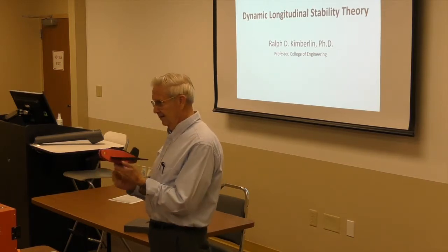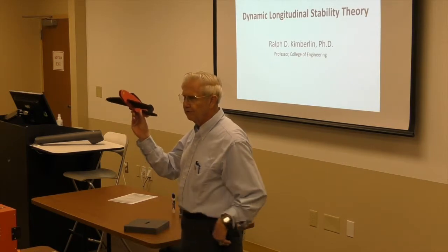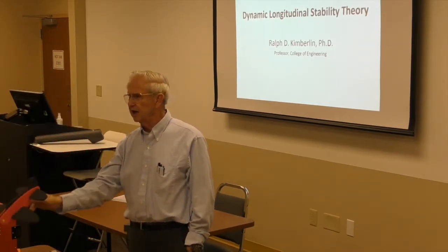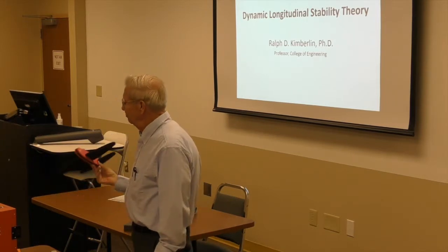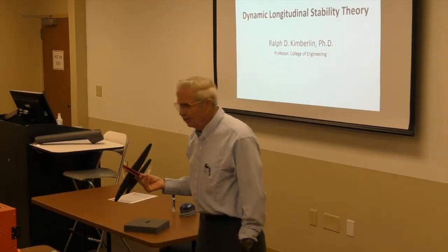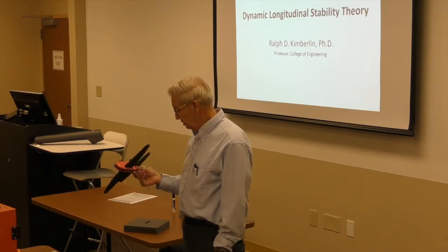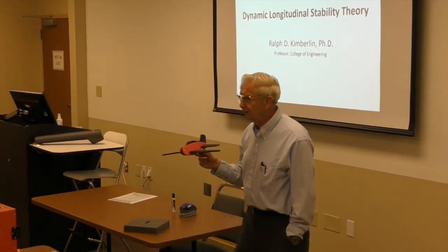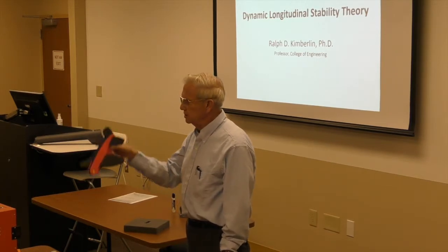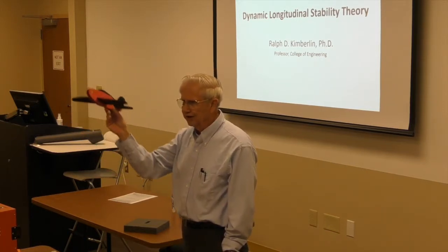Okay, then we have the next case. In this case, we have neutral dynamic, positive static. We displace it from trim. It tries to return to trim, but it goes right on through and an equal amount on the other side, and it sits there and it'll do that forever. Positive static, neutral dynamic. Generally, you will see that in climb for some airplanes. Although it may exhibit itself in other cases, where I've seen it with airplanes, a Cessna 310, for instance, if you displace a Cessna 310 from trim in a climb, it will sit there and oscillate all day, as long as you continue to climb.